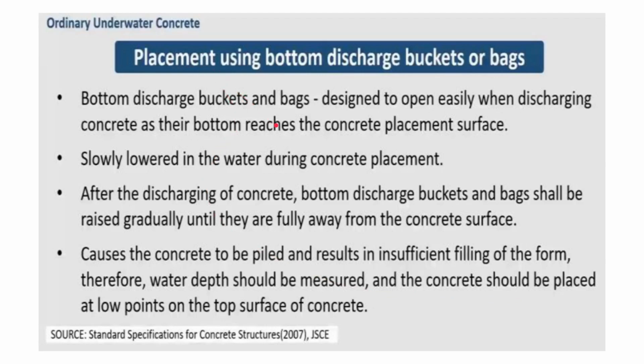Now that was all about concrete pumping. Now let us see about buckets, discharging buckets or bags. So bottom discharge buckets and bags are designed to open easily when discharging concrete as their bottom reaches the concrete placement surface, slowly lowered in the water during concrete placement. After the discharging of concrete, bottom discharge buckets and bags shall be raised gradually until they are fully away from the concrete surface. Otherwise it causes the concrete to be piled and results in insufficient filling of the form.